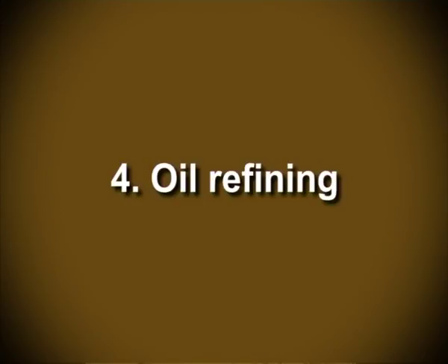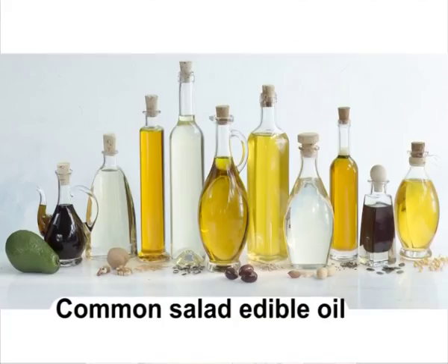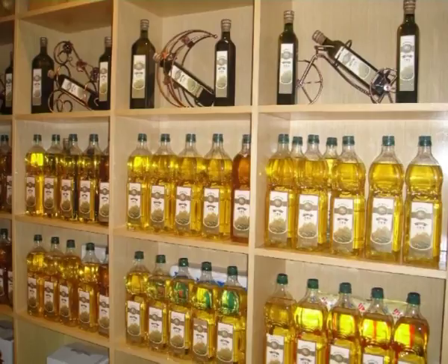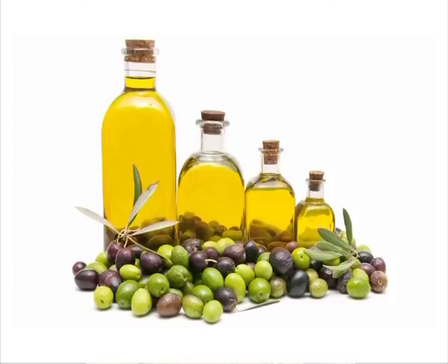Number 4. Oil refining. Rice bran oil is yet to find application as an edible oil in our country, although this is used as a common salad edible oil since long in some of the foreign countries. Rice bran oil is not only high in acid value in crude state but contains a considerable amount of wax, unsaponifiable matter and minute ingredients as well as a large amount of coloring matter difficult to bleach. It is said to be the most difficult oil among all vegetable oils to refine.